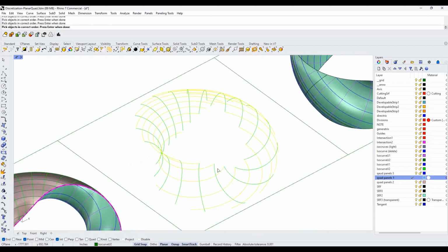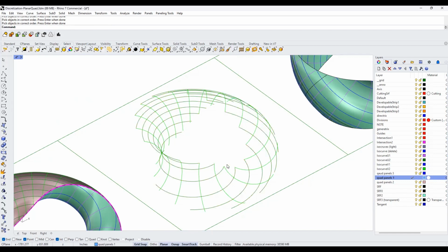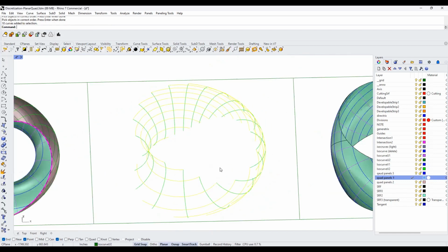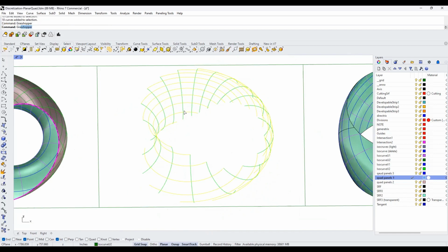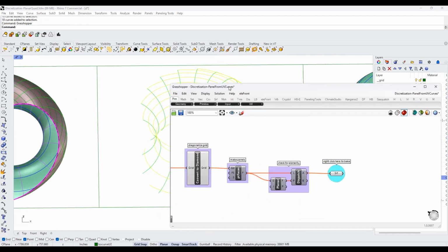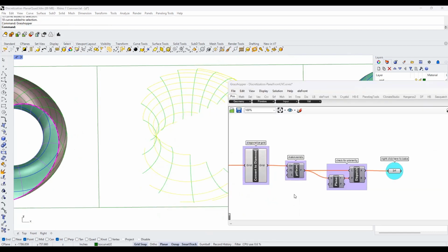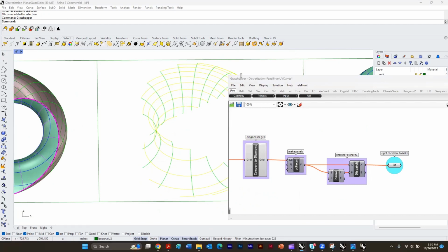So because you're going around and creating them in all sorts of willy-nilly order, when you actually go to use the script, it won't know which order to position them in its memory in order to try to create a grid of points. So the easiest way to solve that problem is to just reorder the curves themselves before you convert them to points.